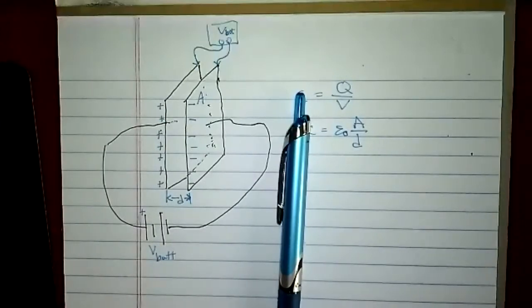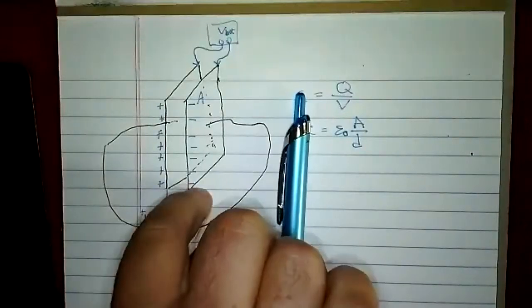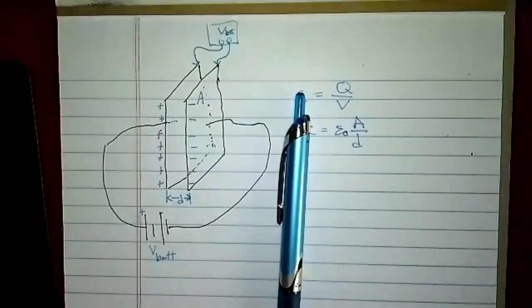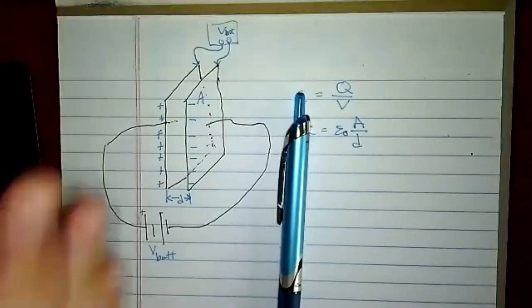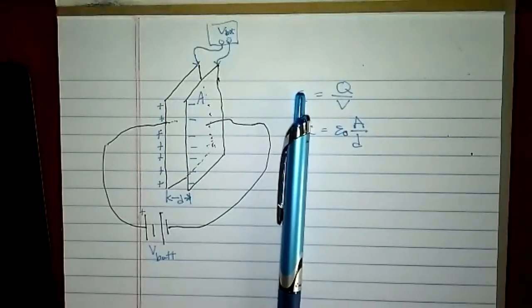Remember me talking about lightning? So there's a chance that the air will act enough like a conductor where the positive charges will jump the space and get in there to the negative side. At that point, you've broken the capacitor. So yes, you want to make the distance between them as small as possible, but that runs into real physical problems. If you got them too close together, eventually you'd see a lightning strike go from the positive one to the negative one, or actually more likely from the negative one to the positive one. So you've got some limitations on that.